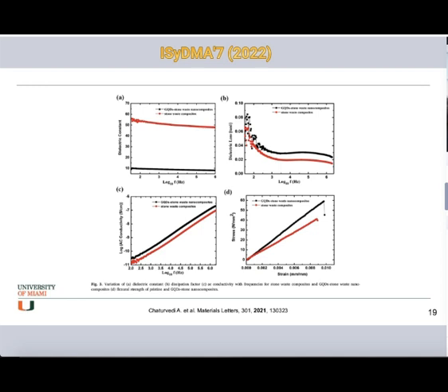The main explanation is the nanoscale size and conducting nature of the carbon dots produced. The carbon dots at the epoxy stone interface may restrict the dipolar polarization in the interface region, which may also block the orientation movement, so a drastic reduction in dielectric constant was achieved.